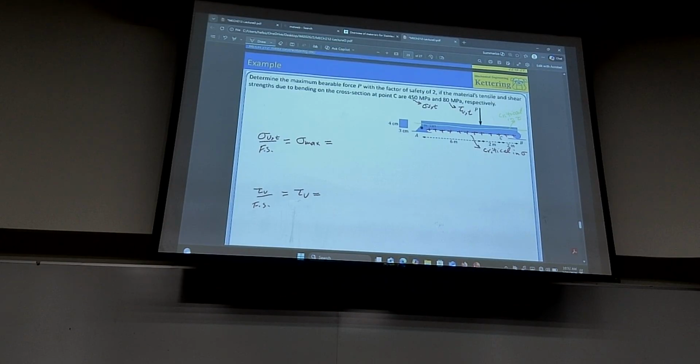do substitutions. So Jacob, please remind us the two equations, one for sigma for bending, one for tau. But remember that it's rectangular, so use the easier one. So for sigma, it is MC over I. Tau is 3V over 2A. Very good. And C in particular is C of bottom, because we're looking at the bottom face.